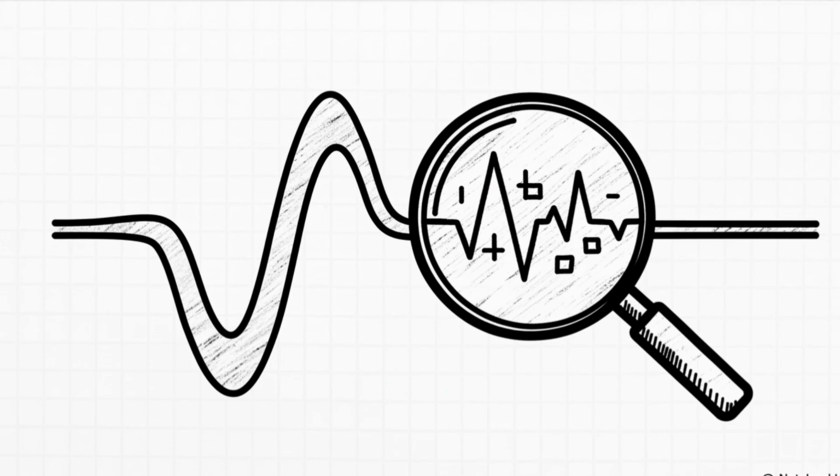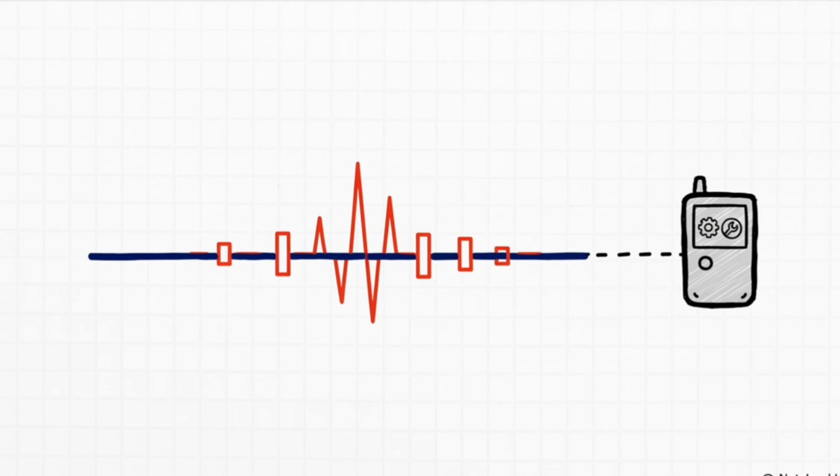So at this point, you're probably thinking, okay, I get it. It's a clever, old-school analog signal, right? Well, what if I told you this old dog has learned a very cool new trick? What if I told you it can also speak digital? And it can, thanks to something called the HART protocol. This is a truly brilliant piece of engineering that piggybacks a low-level digital signal right on top of our trusty analog current. It's like sending a secret text message along with a phone call. It doesn't interfere with the main measurement at all, but it lets a technician talk directly to the instrument, maybe from a laptop in the control room. You can run diagnostics, change its settings, all without ever having to go out into the field. It's this kind of adaptability that keeps a decades-old standard on top.